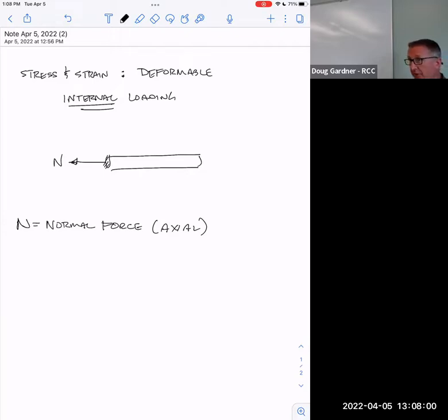Now last term we actually had this. That was a part of something we did, but our forces were always vertical, and so there was never any need for any resistance there. We never had to have any structural strength in the axial direction, so we didn't even write that down most of the time, but we're going to need to today. And then last term we also had V. Anybody remember what that stands for? Which is weird. That was on our free body diagrams.